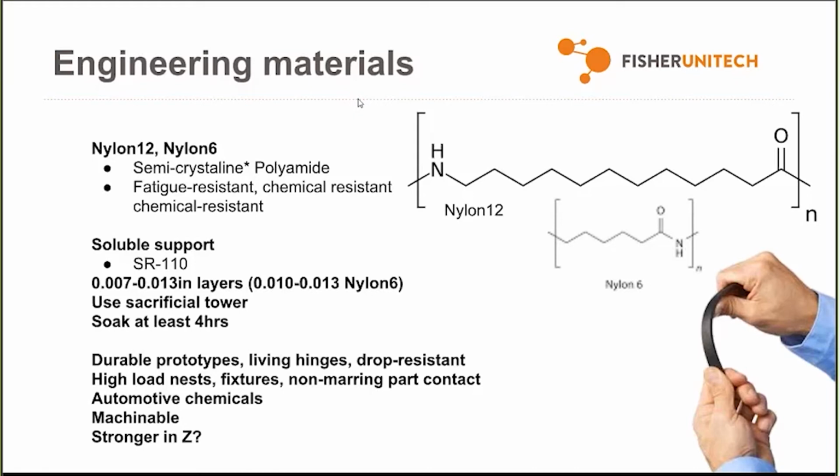Anyway, the other thing about that hygroscopic nature: we're basically printing the material in its dry state, and after it's printed, it needs to be conditioned, as it's called, or basically rehydrated, in order to get the full properties that you're promised. So be sure that you soak nylon parts in the soluble support tank for at least 4 hours.